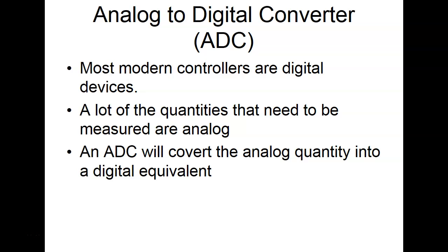Like I said, your meter is extremely accurate, so it uses what they call an integrator, which is really neat. And it's set on a number of counts. So one of the things when you buy a meter is you're looking at the number of counts that's available. The higher the count, the more accurate the meter will be. You can tell by the way the meter ranges. If your meter ranges on 199 or something like that, then it's a 2,000 count meter. If it ranges on 399, then it's a 4,000 count meter. If it ranges on 599, then it's a 6,000 count meter, and it would have a lot higher resolution, but it would cost a lot of money.